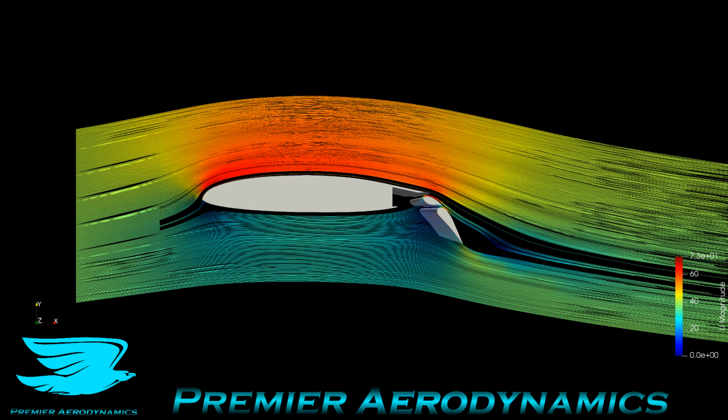dramatically. So to give you an idea of what wing flaps can do to the aerodynamics of a system, a typical airfoil, the maximum lift coefficient you can achieve is probably between 1.2 to 2, depending on how well it's designed. This system, which I've done CFD on here, you can see the streamlines, they can achieve, this is actually 3.16, the lift coefficient. Now the drag coefficient is also quite high, it's 0.155, which indicates that there is some stall, and we'll see later where that stall is occurring.